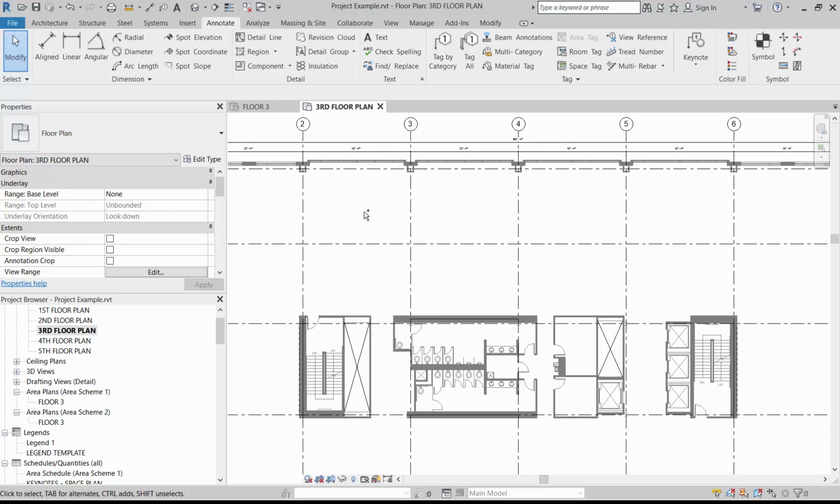In this session, we will be covering the space planning strategies in Revit utilizing design options. You can start a design option just on the existing floor plan and create multiple variations of the floor plan all in the same model at the same time. So we're going to look at a few different ways of doing that.